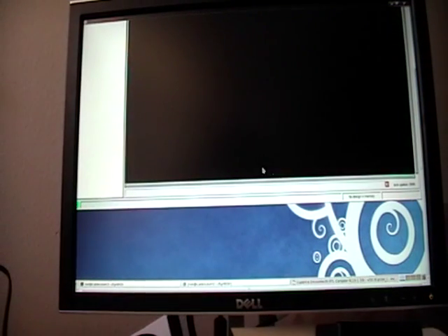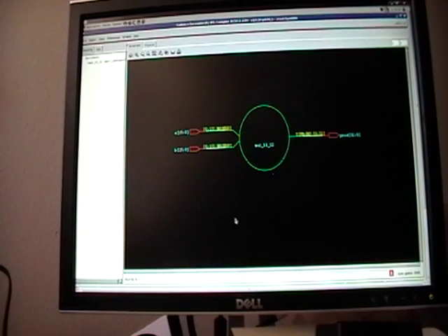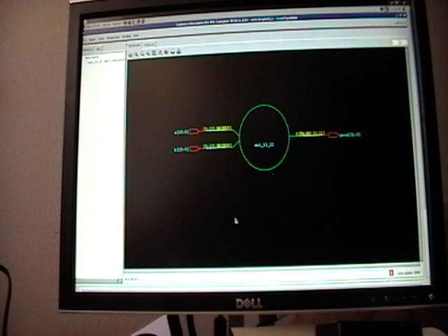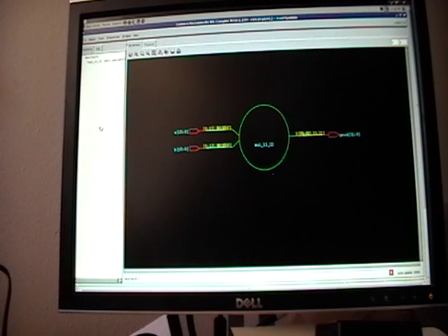Okay. What happens to that is before it can go into silicon, it has to be turned into gates, and then after it's been turned into gates, it needs to be turned into transistors. And here's the input to that circuit that I just showed you. Here's the output. If you go over here, you can see the hourglass is going on here. So it's taking that one line of code and it's turning it into gates right now. And this step is called synthesis.